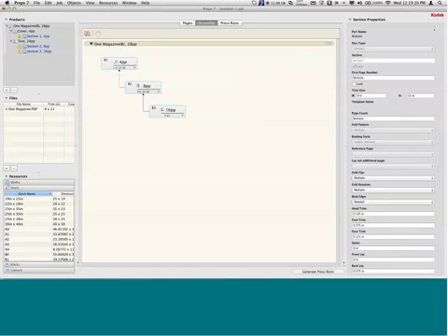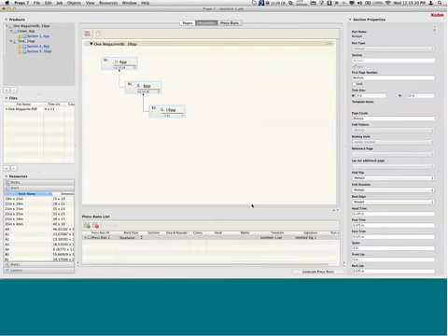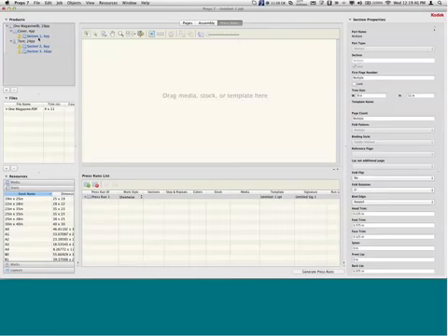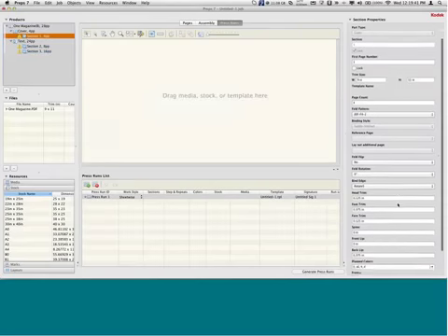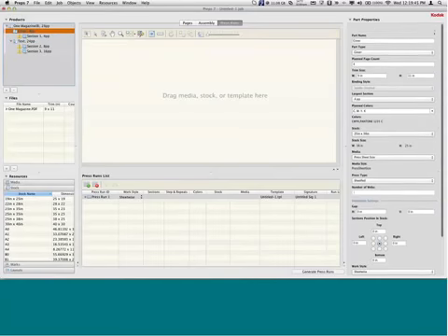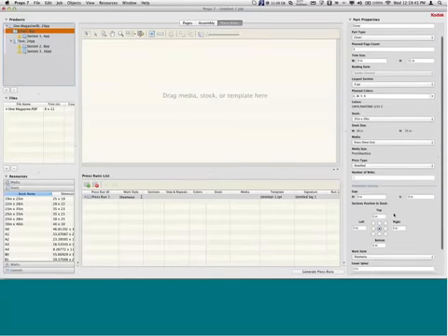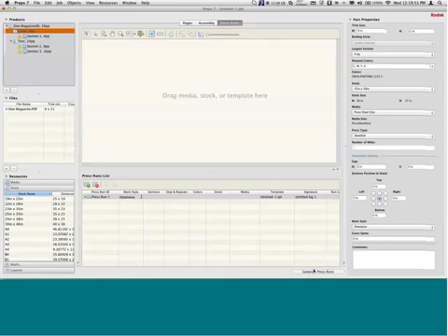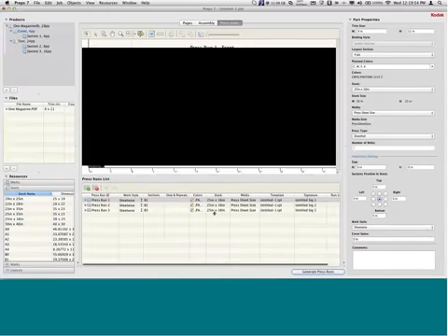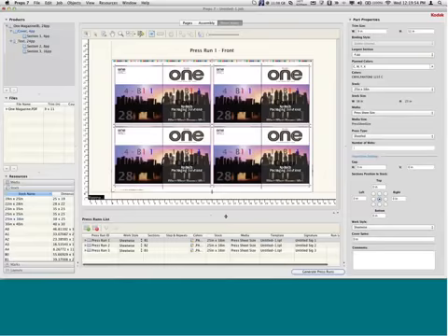And if I go into my press runs view, you'll notice I don't have any kind of imposition. But because I've programmed everything, and because each of these individual sections has its binary information, each part has also got some sheet details, I now can hit Generate Press Run, and Press will take that information and present for me a result.